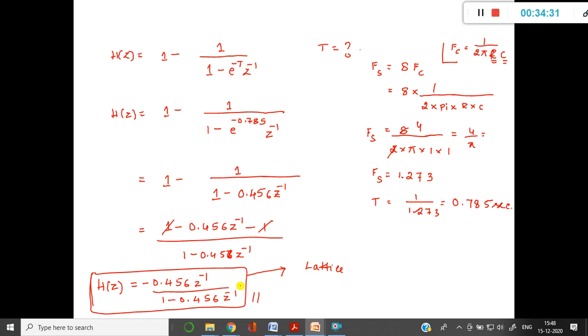This you have already learnt in your signals and systems, how to represent in the form of the block diagram, what we call the cascading lattice structure. There, z inverse indicates one simple delay. To generate that amount of delay, we apply flip flops, because a flip flop is what is called a delay element, right? That's it. Any doubts here in this case?